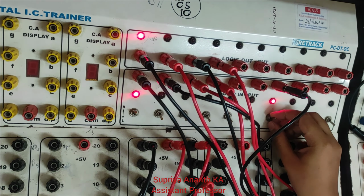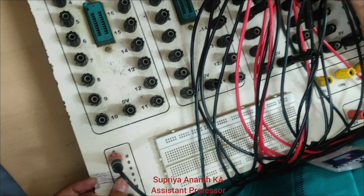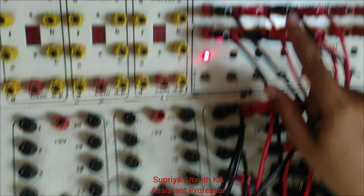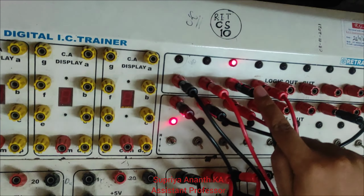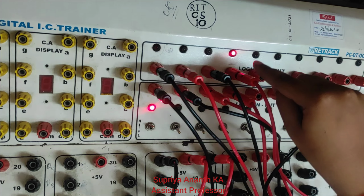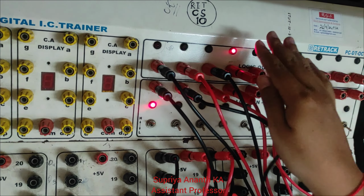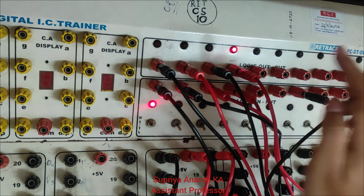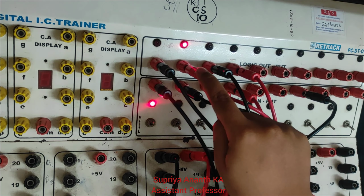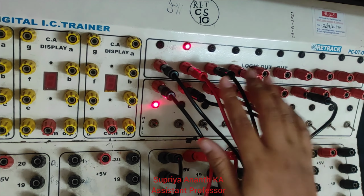Now I will disable this mode and press the clock pulse. For every clock pulse I give, the value should be shifted. Now I am giving the clock pulse, the value is shifted. Once again, one more clock pulse, the value is shifted. The value 1 0 0 0 is being shifted for every clock pulse. Here A is 0, B is 1, C is 0, D is 0. So this repeats for the ring counter.